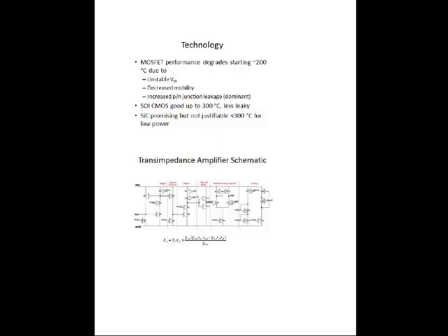When you design an oscillator, you don't care about the loop gain, you just make sure that it's greater than 1. So this amplifier's gain varies with temperature and process. For capacitive sensing, the resistance needs to be calibrated.